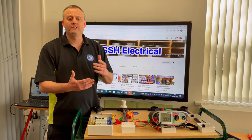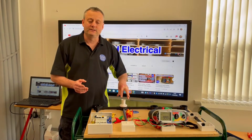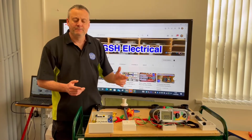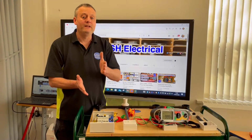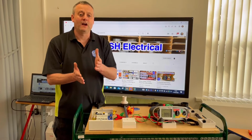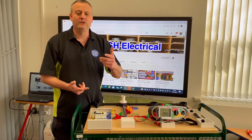We then put all our covers back on. We left our switches in the on position. We made sure we didn't have any loads in circuit, so in this case the lamp wasn't connected, and we carried out that insulation resistance test, expecting to have a very high value. We don't expect the PVC to have started to break down or deteriorate over time, and we got a reading greater than the machine could read.